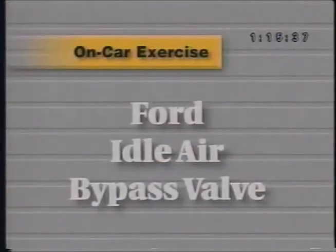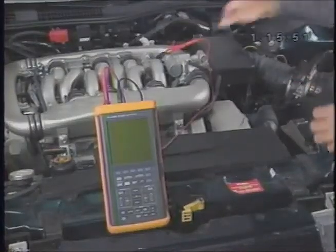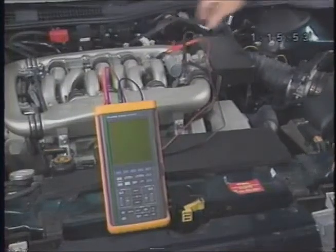In this exercise, you'll see how to use Scopemeter to view a Ford idle air bypass signal and see what that signal tells us about the engine's adjustments and condition. Start with a cold engine so you can see how the idle air bypass signal changes as the engine warms up. Connect the channel A probe to the negative side of the idle air valve and the ground lead to a good ground.